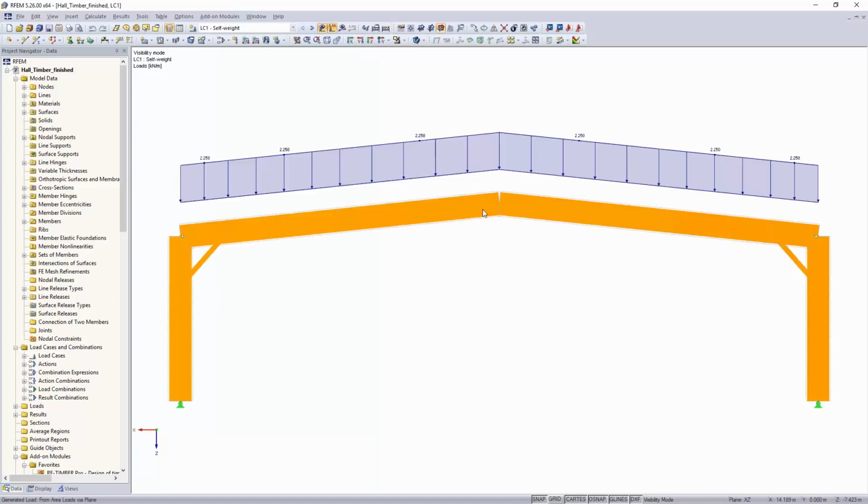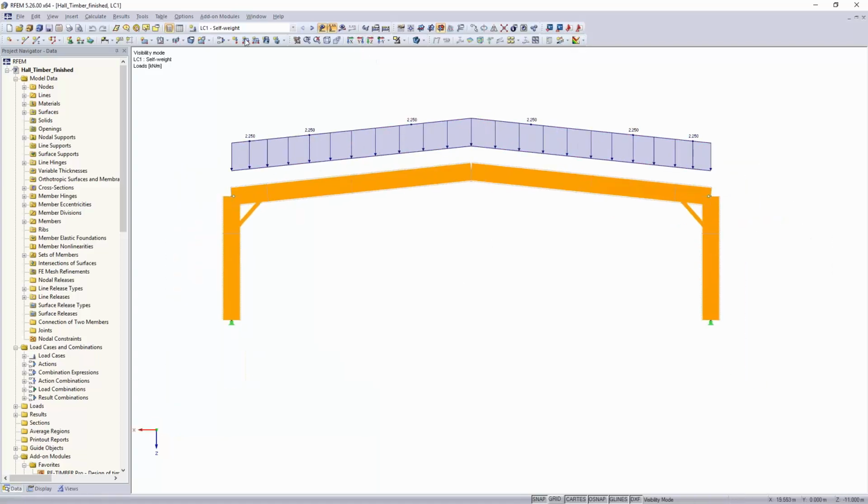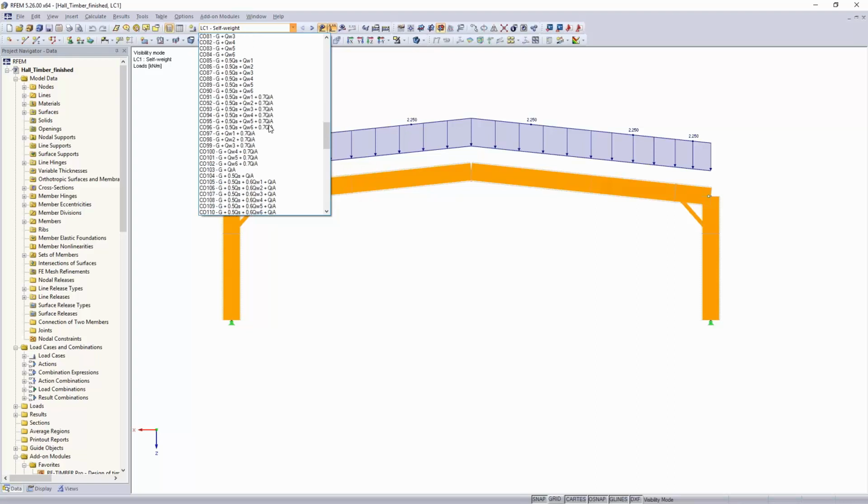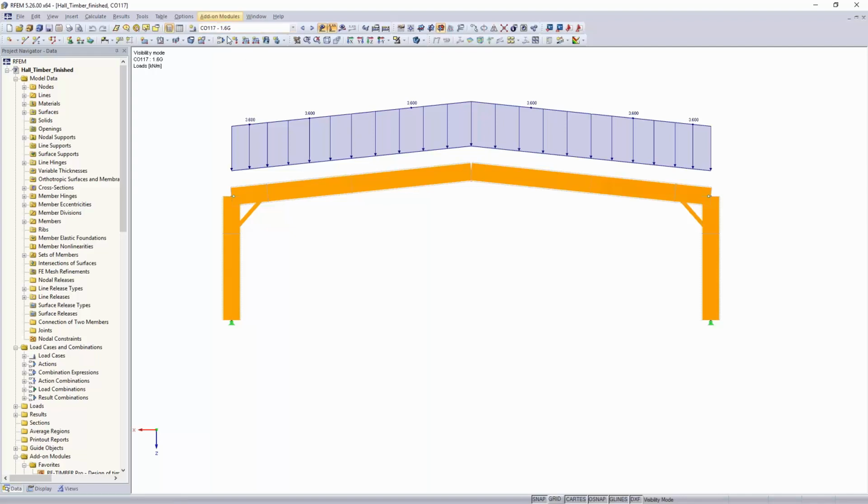Let's have a look at the serviceability limit state in combination 117. You see that in order to regard the creeping, the software increased the load by a factor of 1.6. Andreas mentioned that last week. Now, how could you do that in case this was a highly nonlinear system? Because then increasing the load will not regard creeping correctly. That would work via copying this and reducing the stiffness. That's just one way how you could do it.